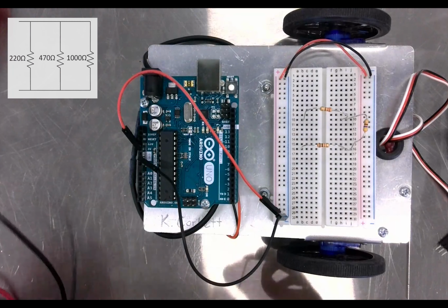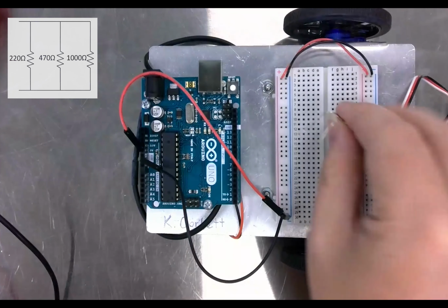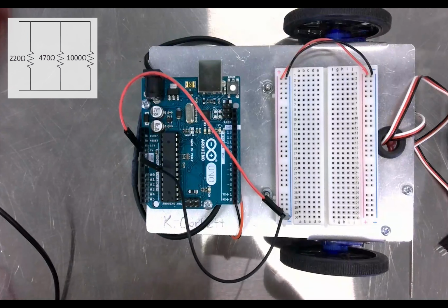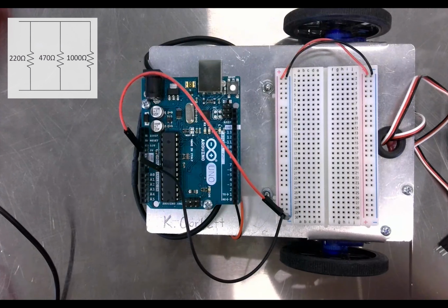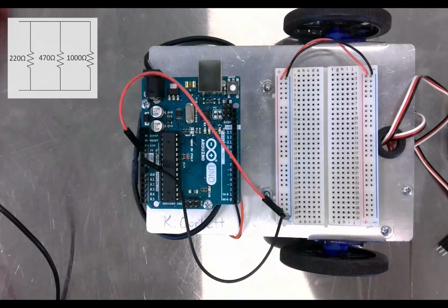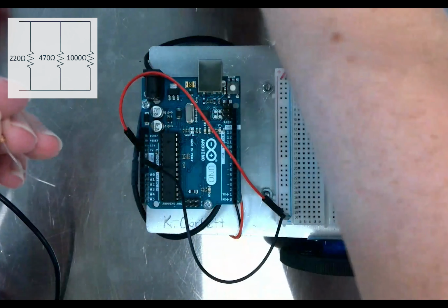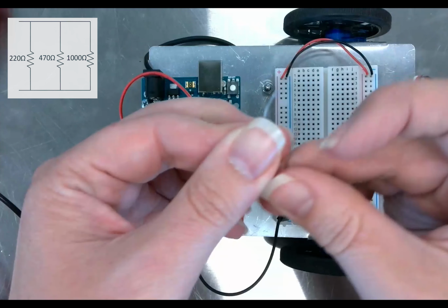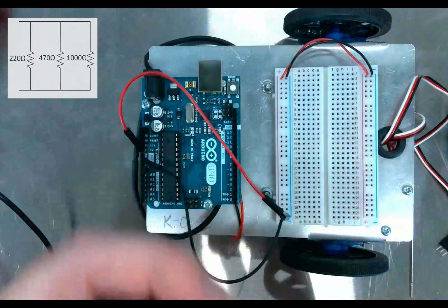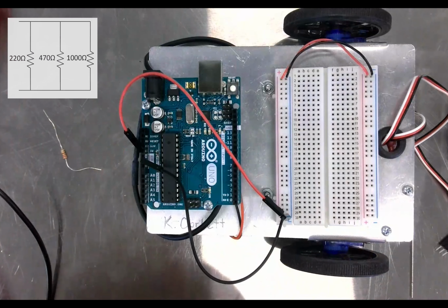Now, let's switch to parallel circuits. So looking at the parallel circuit that's shown on the screen, let's rebuild this circuit as parallel. Now notice how in the parallel circuit, all of the resistors are connected at the top and all of the resistors are connected at the bottom. So one side of this resistor should be connected to one side of this resistor. So if you were looking at these two resistors, these should be connected here, and then the bottom should be connected here. So how do you put them on the breadboard such that they're connected? You put them in the same rows.